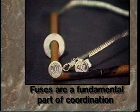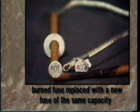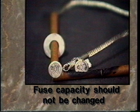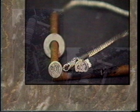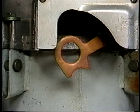Operating the cutout. Fuses are a fundamental part of coordination in the electrical distribution system. It is critically important that a burned fuse be replaced with a new fuse of the same capacity. Fuse sizing is determined by a coordination study of the line. Fuse capacity should not be changed unless a study indicates that the system coordination will not be adversely affected by the change.